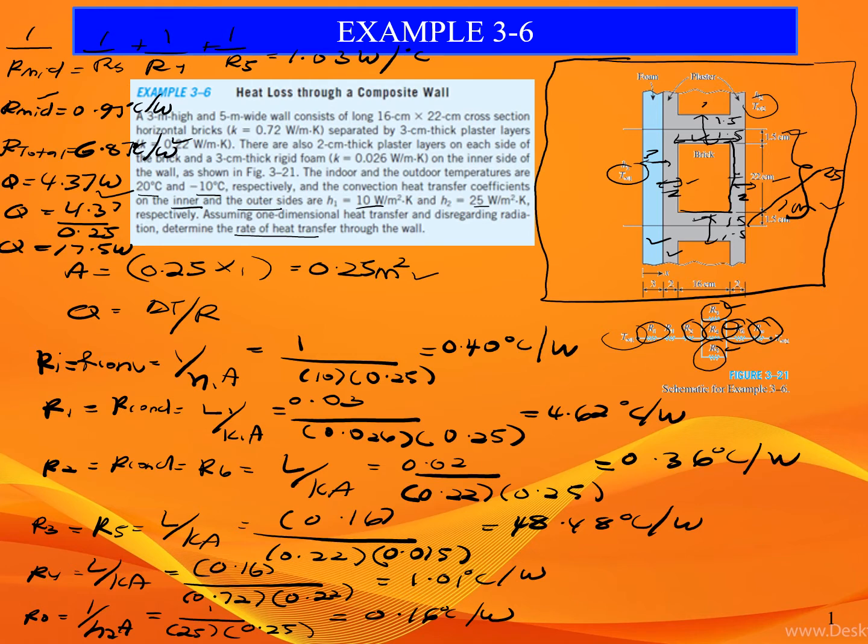Okay, this is per meter area. The heat transfer is per meter area. So you need to know for the whole area 3 meter height times with 5 meter wide, I continue at the bottom, Q equals 17.5 times with 15, and then you will get 263 watt.